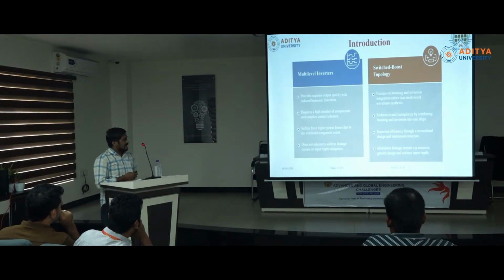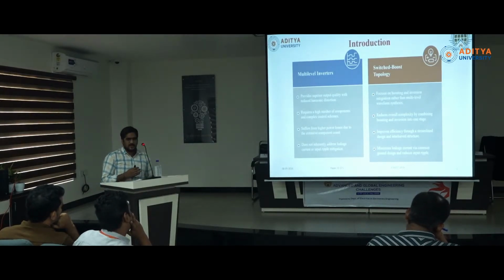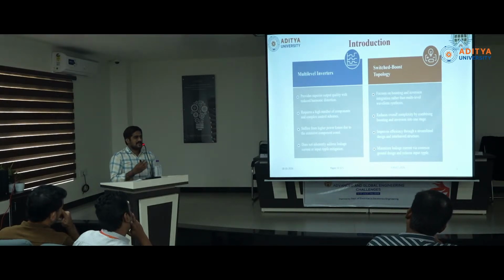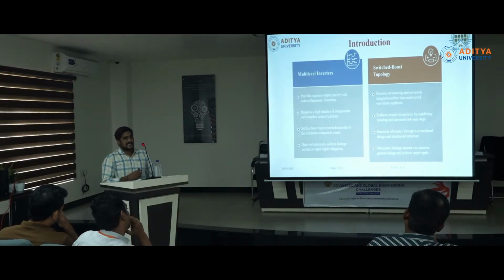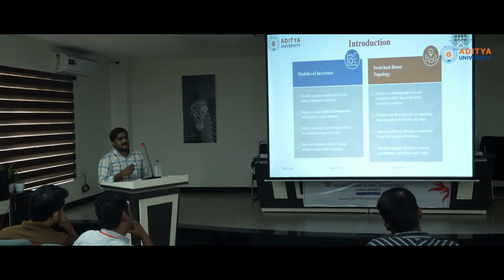Generally, multi-level inverters produce high power quality with the increase of the number of levels. If you increase the number of levels, obviously we use more switches, so we have different reduced-switch topologies to improve and reduce the THD also. Here we go with a switched boost topology. We are using a transformerless DC to AC conversion, as we need to integrate the DC source to the grid. For dynamic voltage change, we are using a switched boost topology.